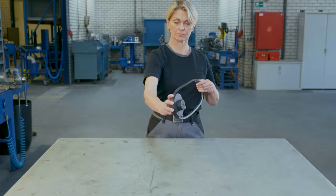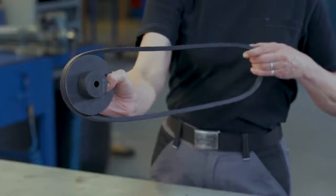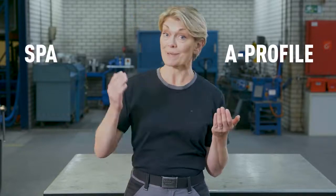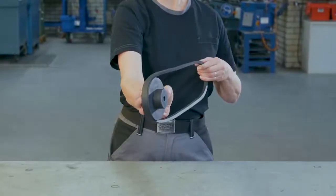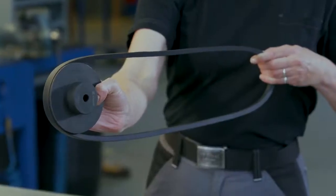The profile size needs to match the pulley type. So, for example, the A profile is paired with an SPA type pulley. The B profile is paired with the SPB pulley, and so on. It's important to find an exact match, as belt profiles and sizes are rated for different loads.